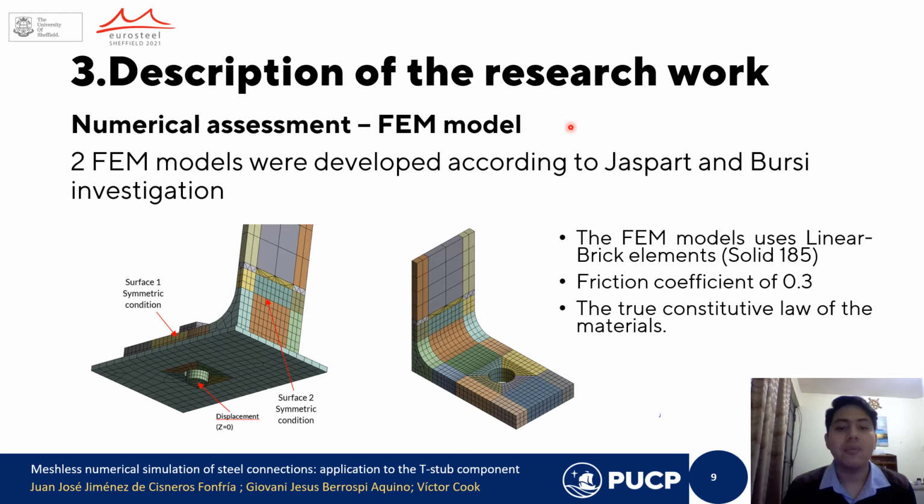Numerical assessment, FE model. We developed two FE models according to Jaspart and Demonceau's investigation. These FE models employ linear brick elements from the available library of ANSYS. The SOLID185 element was employed. A friction coefficient of 0.3 between the washer and the flange was used, and the true constitutive law of the materials was employed in the simulation.